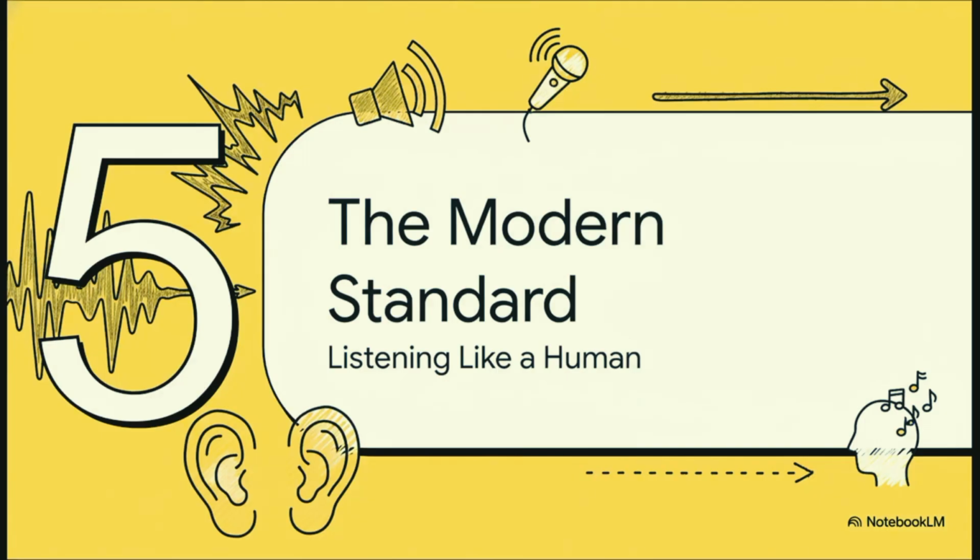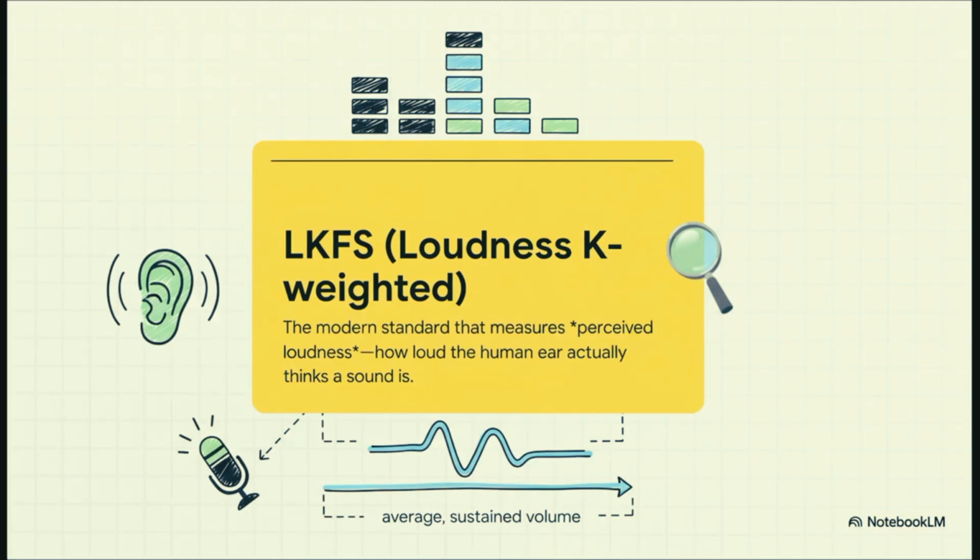So, that massive difference between what the meters said and what we actually heard forced a revolution in the industry. People realized they needed a totally new way to measure volume, one that wasn't based on technical peaks, but on, well, on how humans actually hear. And that's where LKFS comes in. Seriously, this was a game changer. LKFS is a much smarter standard. It uses a clever algorithm that's designed to listen more like a human ear does over time. It doesn't really care about quick, sudden peaks, like a single gunshot. It cares about the average sustained loudness. In other words, it measures the experience of loudness, not just the raw signal.